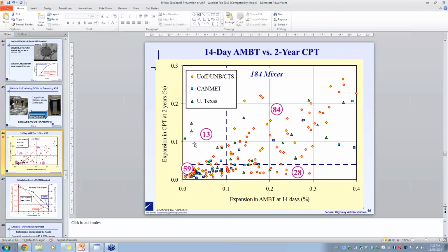But of course, the higher the alkali content in the concrete, the larger the gradient, the faster it's going to leach, just because you've got a higher alkali content. It's obviously something to consider, but I really think that the secret for us is to try and develop an exposure condition where the leaching is minimized or eliminated. I think that would be the preferred approach.